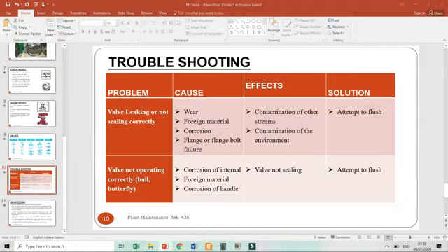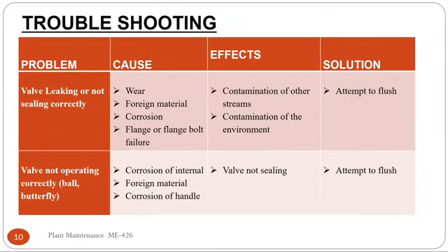There is one important thing to keep in mind, as I have said in my lecture, that valves range from ½ inch or 1 inch to 48 inch. As the size of the valve increases, the force required to open the valve increases. So for bigger valves, 20 inch, 24 inch, it is helpful that the valve is opened automatically, or an instrumentation and control system is fitted. So there is a motor on it. We can have push on and off buttons so that we can open or close it for ease of maintenance.